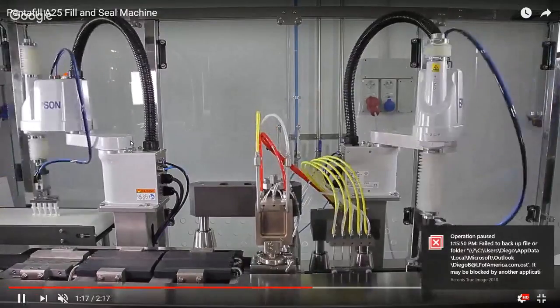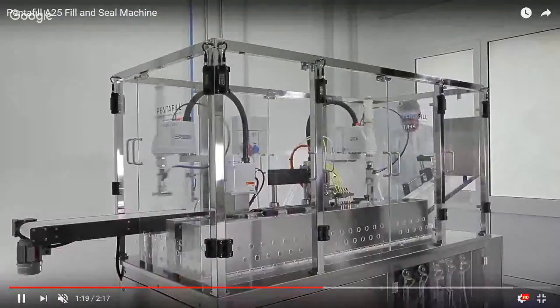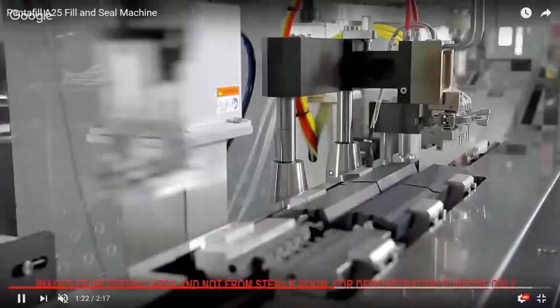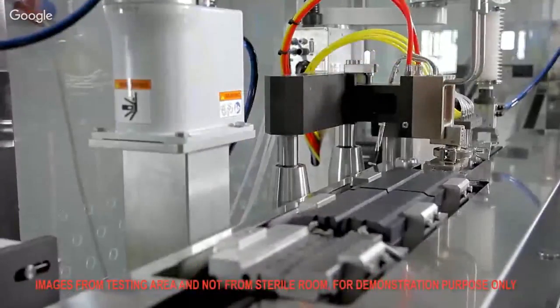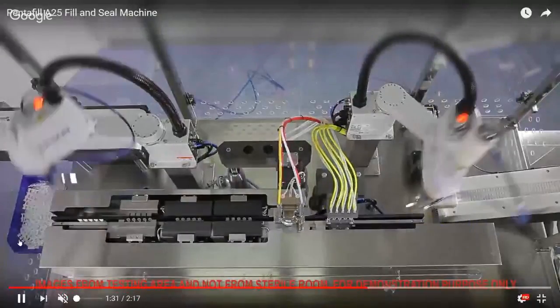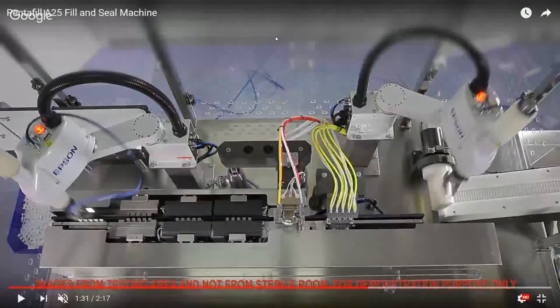Okay. The next station is a hot air. Basically, we blow hot air on the plastic to soften the sealing area. Let me stop the video at this point. We have a nice close-up from the top. So we blow hot air on the sealing area to soften the plastic and to make the sealing process better. Now, a very important thing is that when we blow, the hot air does not come in contact with the product, because it is blown horizontally, so it does not go inside the vials. It does not contact the product.